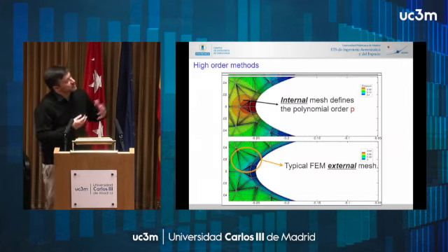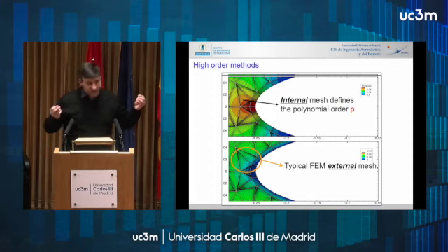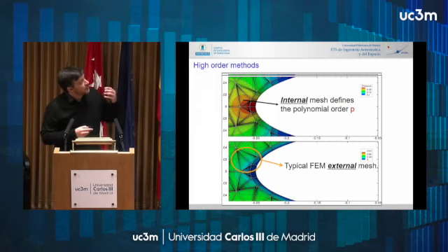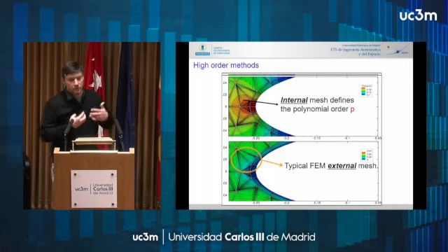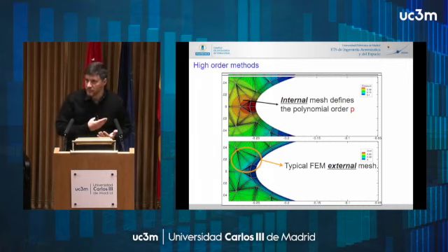In fact, what we're doing is increasing the number of points that we have inside each triangle, right? We need certain points to fit a polynomial. So if you see a higher-order mesh, what you see is a very coarse mesh, with very, very large elements, and you think, okay, this is very badly resolved, this is a pretty poor mesh. But in fact, because you're using a higher-order polynomial inside, you can represent every inner point, and those are the effective degrees of freedom that you're using.